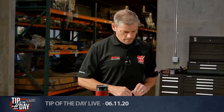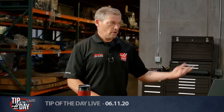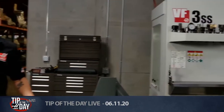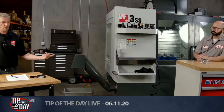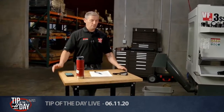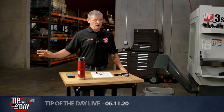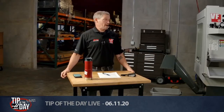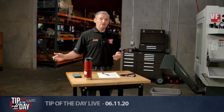Let's move on to, okay, Slugs asks, this is from a week or two ago as well, a machine like a DM2 where the anchor kit is almost mandatory, does it require more concrete or is it more heavy cut related? And we were having a little bit of a discussion about this. If you go to our website and look at the machine requirements for installation, you'll see that the requirements for a VF2 and a DM2 are exactly the same. We recommend a typical 6-inch slab, just like you would in most industrial areas. And you don't have to do any additional coring or anything like that. You do certainly want to anchor a DM2. And it's not because of heavy cuts, it's because of the extreme acceleration the machine has.